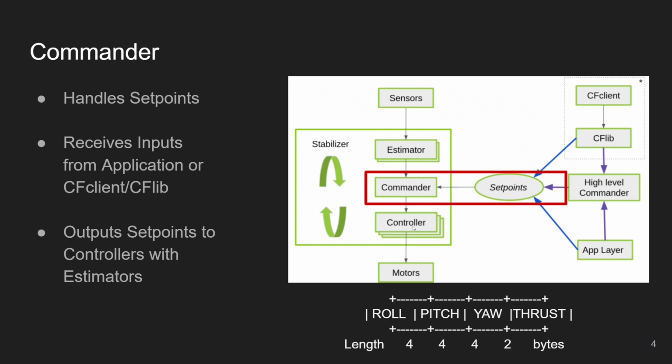It also works to take out stale set points. It determines, based off of a variable factor, how long it's had the set point for. And if it's past some sort of cutoff, then it'll just wipe the set point, because now it's considered stale and it won't actually help with movement of the drone anymore.